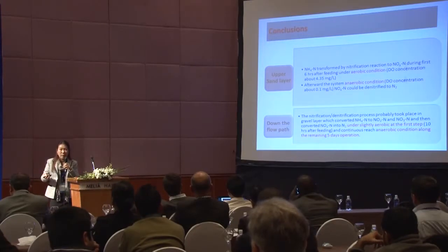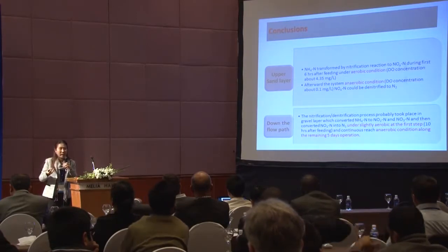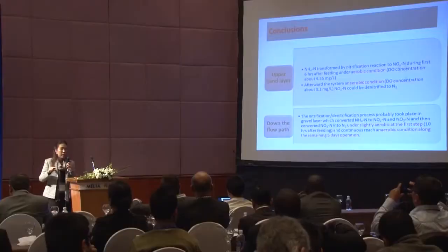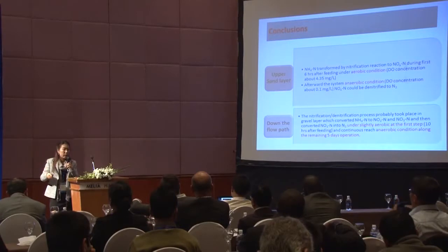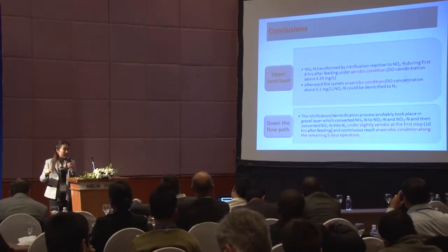Because in my previous study at that time, I had not measured DO concentration yet, but for this study I was also asked a lot how nitrification can occur inside the sand media. Then I also measured DO concentration to confirm the reaction. And also within the sand layer itself, denitrification can occur, because we can also confirm it by the anaerobic conditions.